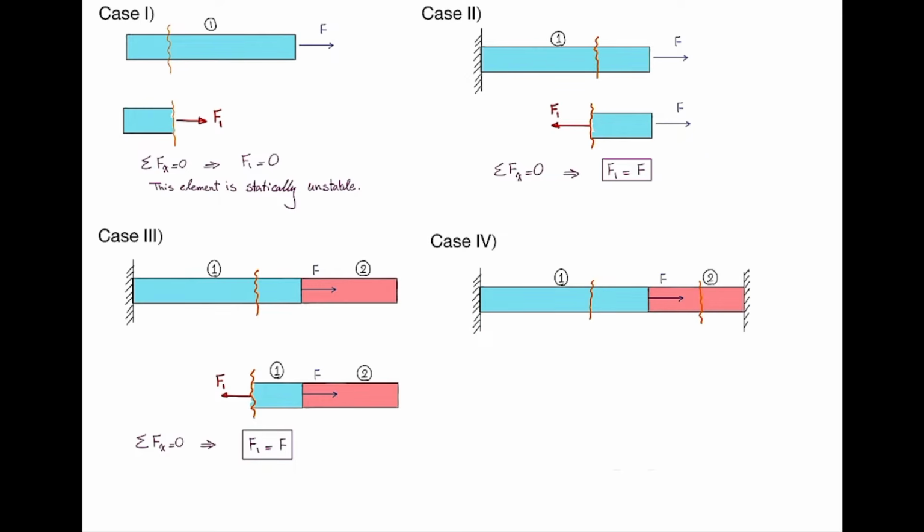If we cut the element, just the blue element, is that part free? Both sides are restrained, so we need to have one additional cut to make the middle part free. So I have to cut it twice as shown here, and then there will be 2 internal forces. Both of them are outward from the surface. We're going to call them F1 and F2.